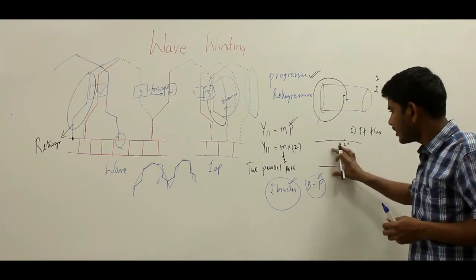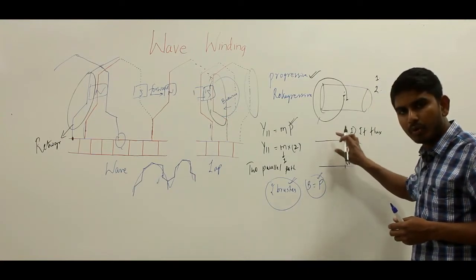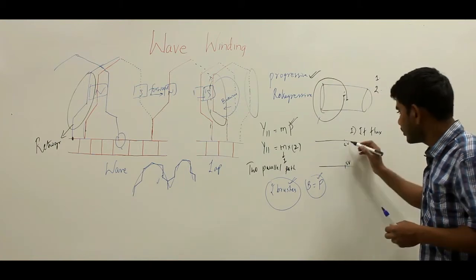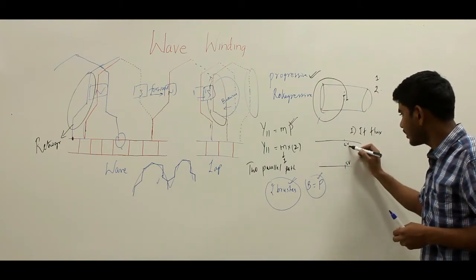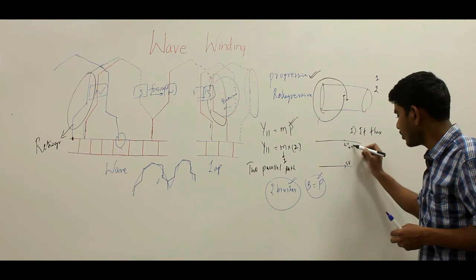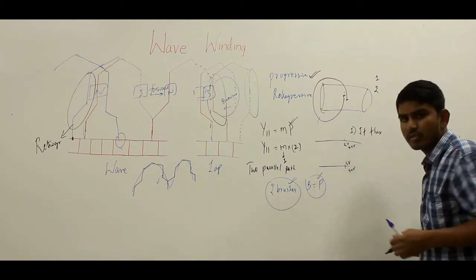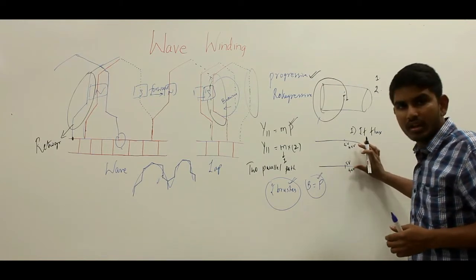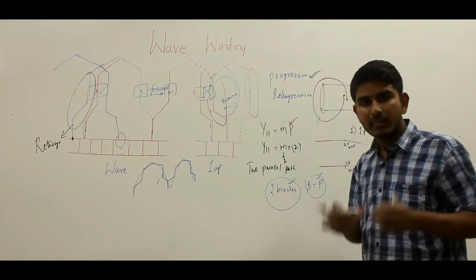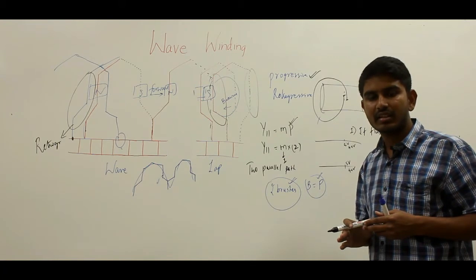As the effect is similar on both parallel paths, suppose due to the unequal fluxes there are 4.8 volts here, and similarly there will also be 4.8 volts there. So the potential across these two parallel paths is maintained constant irrespective of the flux differences.